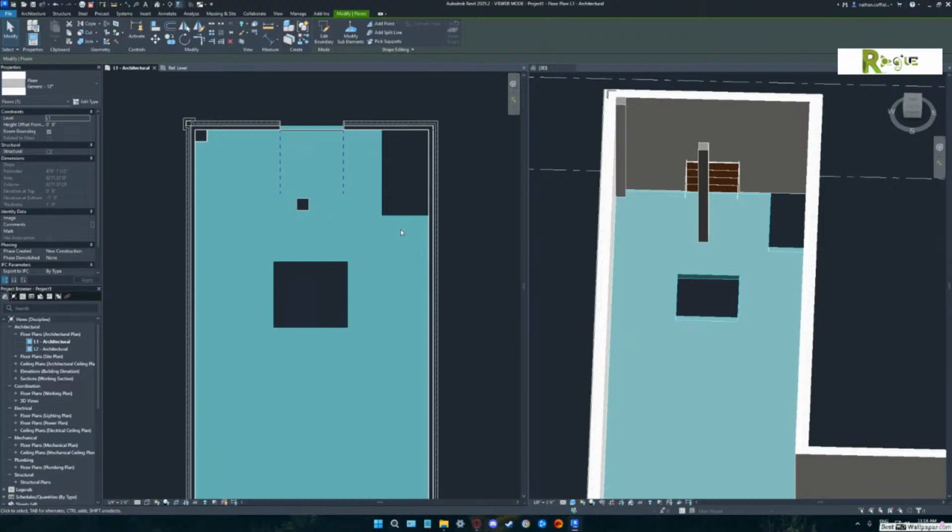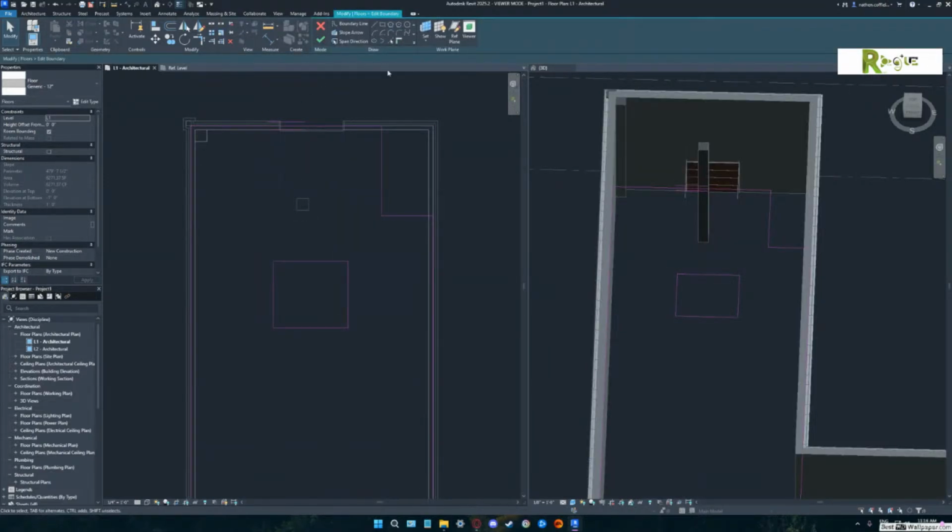The island, you know what I mean by the island. If you have two shapes, one inside the other, it's going to create a hole. If you put a third shape inside that hole, you can actually have a piece of floating slab in there if you wanted to, or floor. Right, because this is just empty space now. Correct. The first outer shape is solid, and if there's a hole, it becomes a hole. And then if there's another shape, it becomes solid inside of that hole.